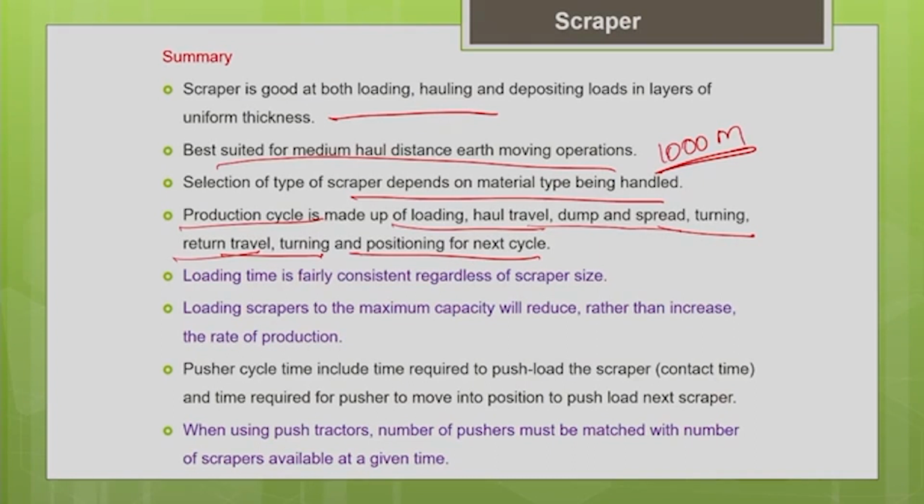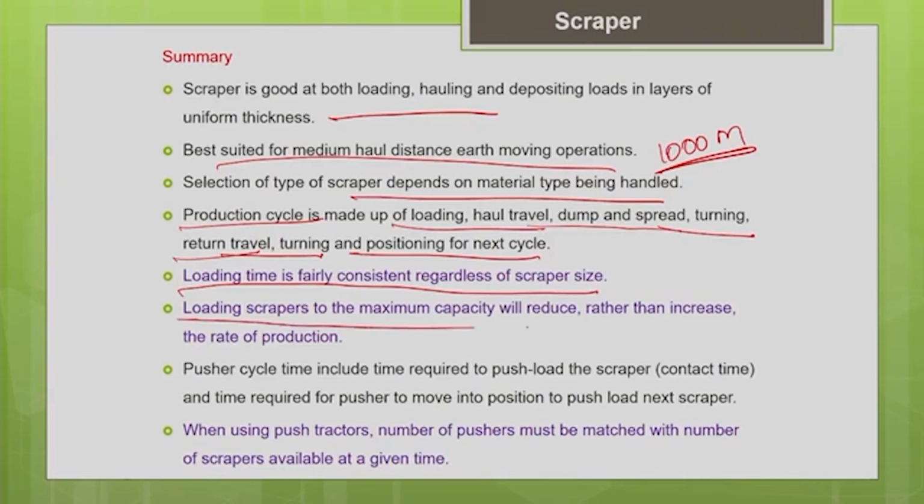We also discussed that loading time is fairly consistent regardless of the scraper size. Whatever the size of the scraper, we have to choose a compatible size of pusher, so the loading time is going to be fairly consistent. Loading scrapers to maximum capacity will reduce rather than increase the rate of production.